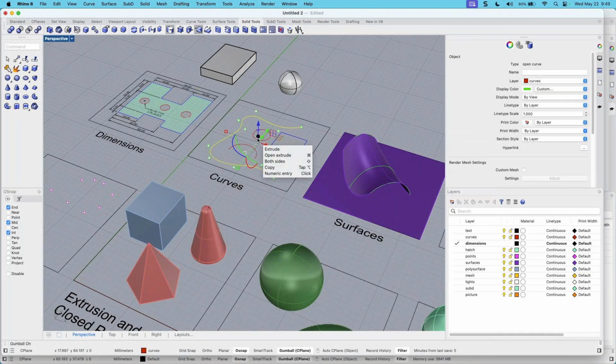And then we added being able to extrude into a surface, and this is an open curve, so we can't create a closed curve, and we get the different options for extruding. But we got a cutter or embosser in Rhino 8. So all that's new. There's lots of tutorials that just cover the gumball, but I need to get you enough of the gumball so we can put together our project for today.